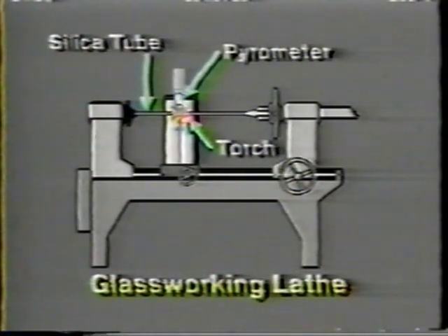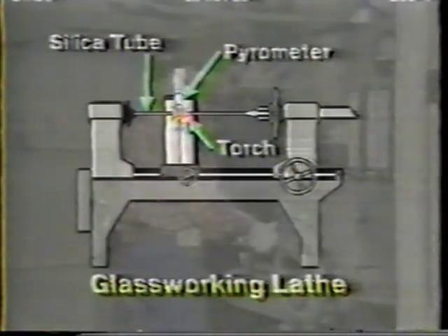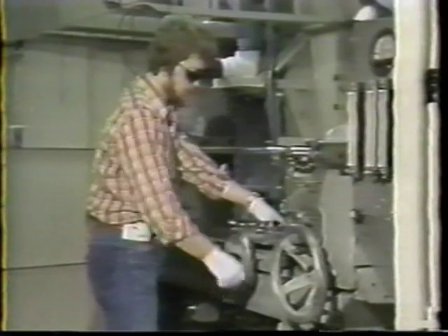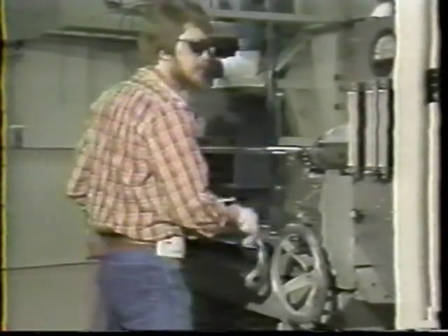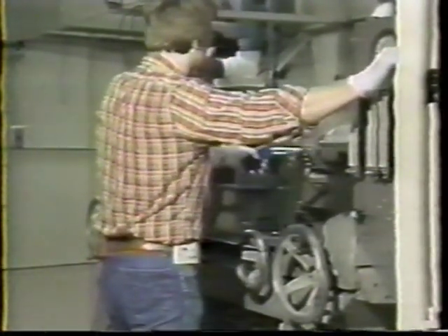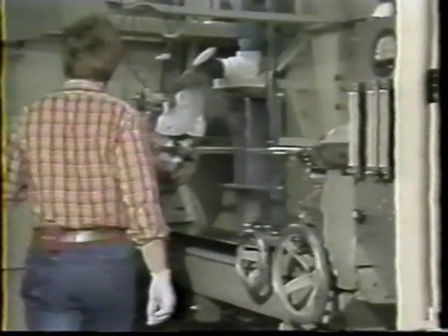An optical heat sensor is constantly monitoring the torch's hot zone temperature. This information is used by the computer to adjust the torch temperature and speed, and route chemicals from the chemical delivery system through the rotating hollow tube. After the hollow quartz tube begins to rotate and the torch is ignited, a mixture of gases including germanium tetrachloride, silicon tetrachloride, and oxygen is passed through the center, causing silica particles to be deposited on the tube wall downstream of the torch hot zone.